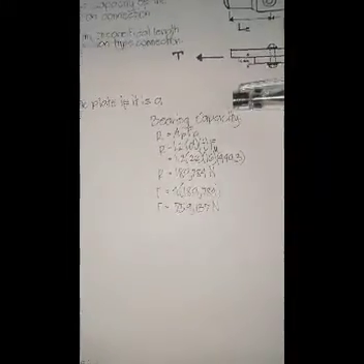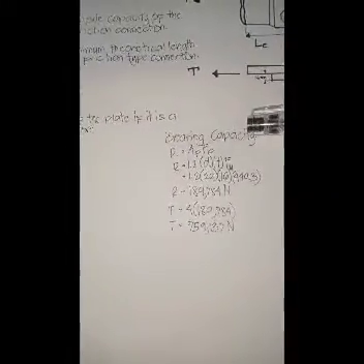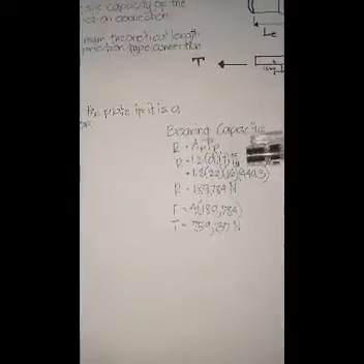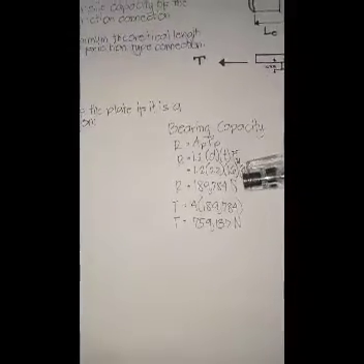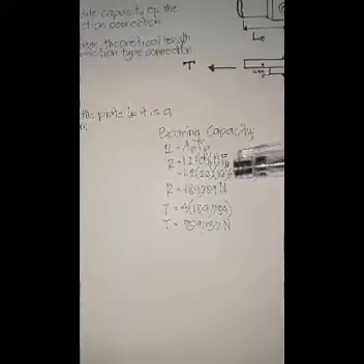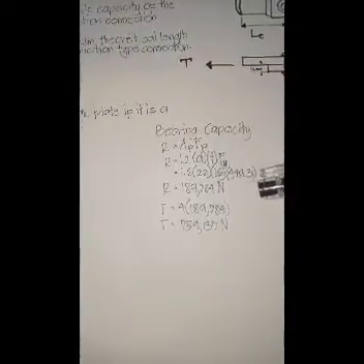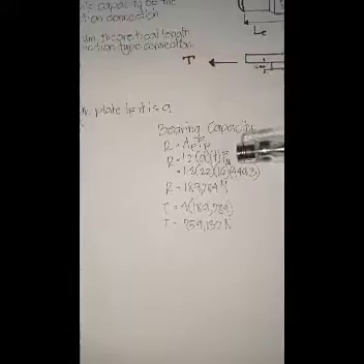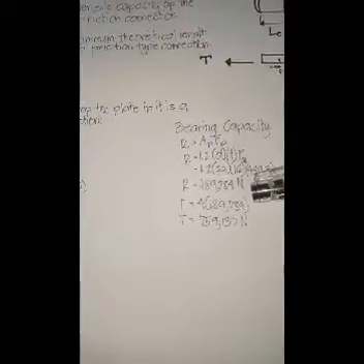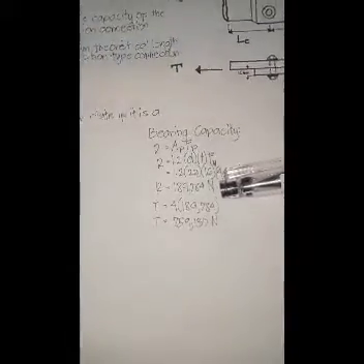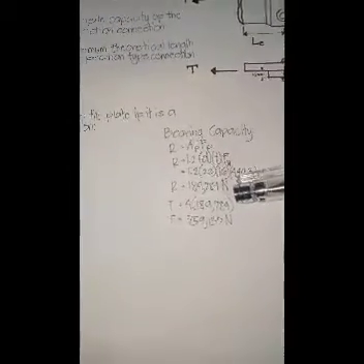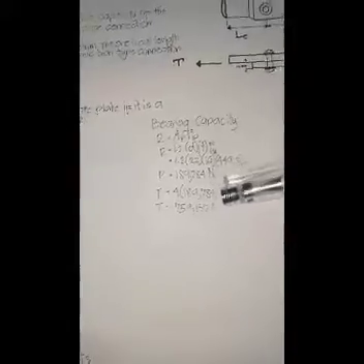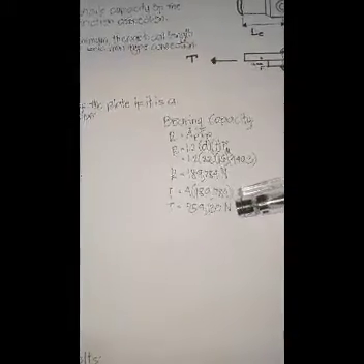Bearing capacity, R is equal to A sub p times F sub p, or 1.2 times D times T times F sub u. Then substitute 1.2 times 22 times 16 times 449.3, which is the value of F sub u. Our R will be 189,784 Newton. Then times 4 again to get the bearing capacity of all bolts. So 759,137 Newton.